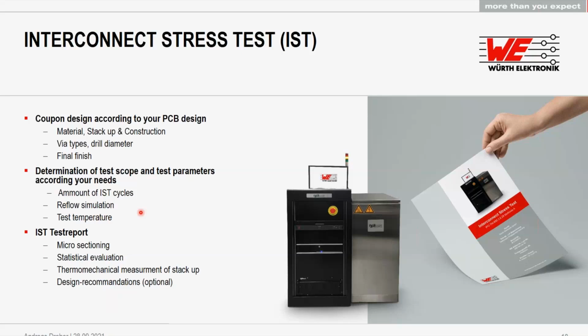If you put the boards through several reflow simulations, like 6 times, you can see that these will really stress the boards. Afterwards, we can do microsection and statistical evaluations as shown in these slides, thermomechanical measurements to find your CTE value dedicated to your board and your stack up, and maybe get some design recommendations for improvement.